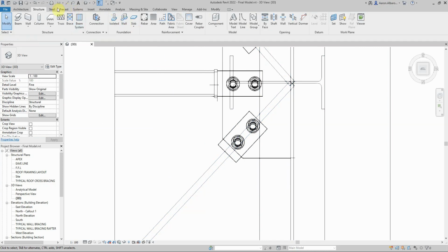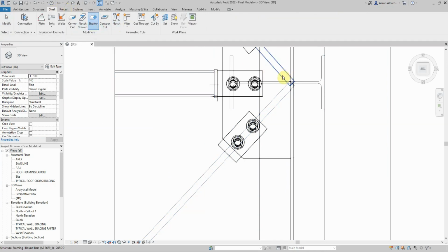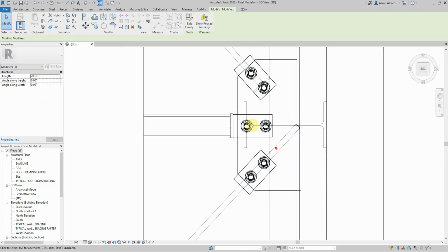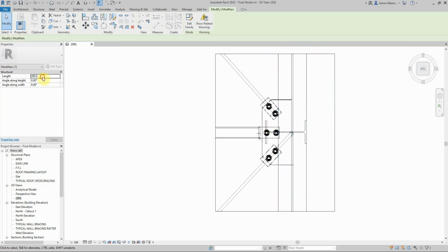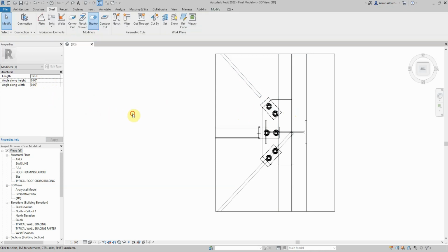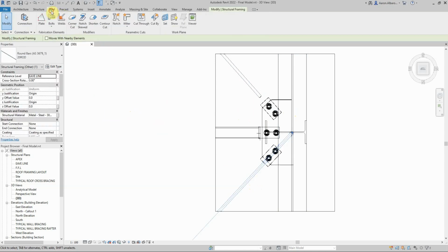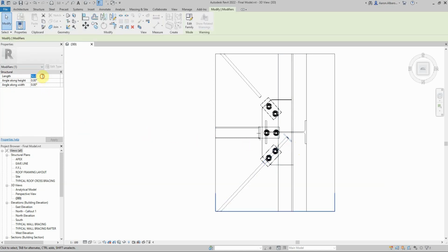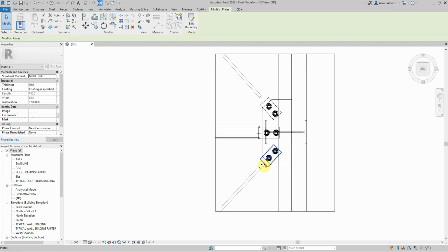rods. So if we go to steel, shorten that by, let's say, 200. See how that's going to work for us. 200 is still too long. Let's make it 350, and that is roughly around where we need it. So let's give it a 350, and I'll do the same here. Steel, shorten that by 350. Apply. Okay, one last thing.